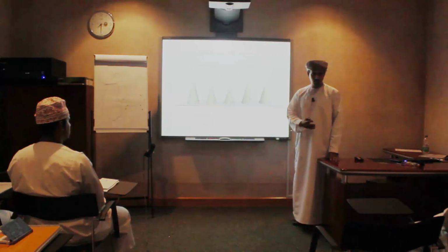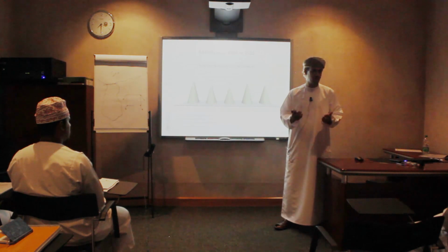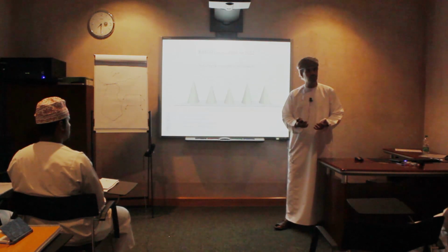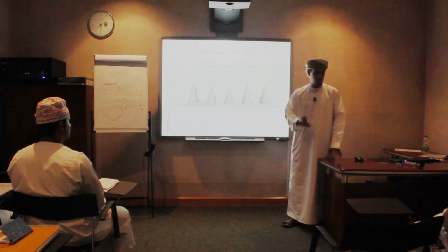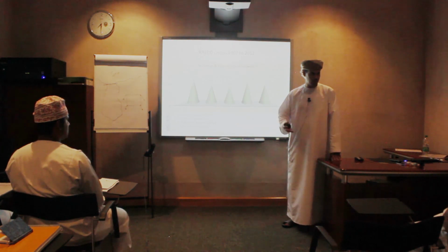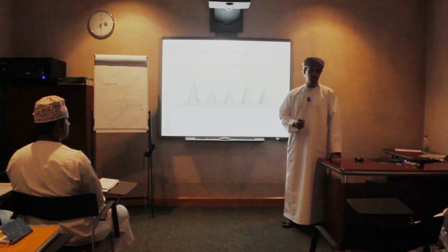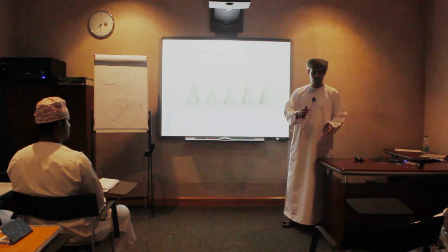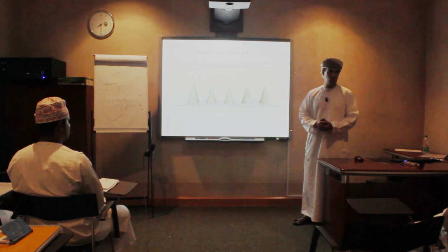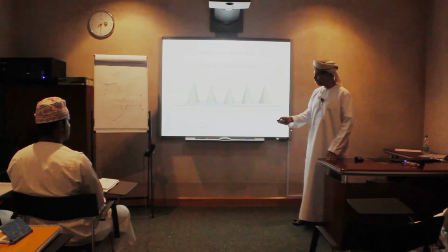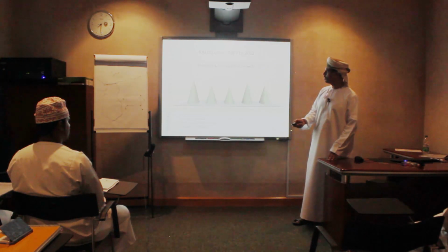With the new meters, you measure the actual consumption, so some bills will go higher than normal. It's not because the new meters are not good, it's because the old meters were really not calibrated a long time ago. Every few years you need to have the meters calibrated to get proper readings. So this is one more way to reduce losses.